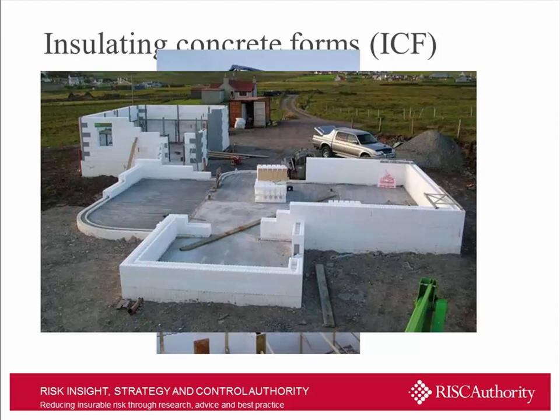Insulating concrete forms is something you may have come across, not so prevalent in the UK, used quite commonly in Southern Ireland, using polystyrene to create formwork, filling the gaps in between with concrete. But again, you've got a combustible cladding material, which if ignited will spread fire very, very quickly indeed. There's an example there of a domestic construction. Sadly, some of the images behind that, which you can't see, also show it being used quite extensively in a more commercial environment.